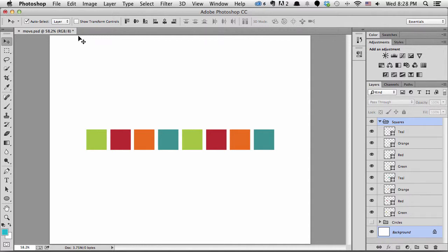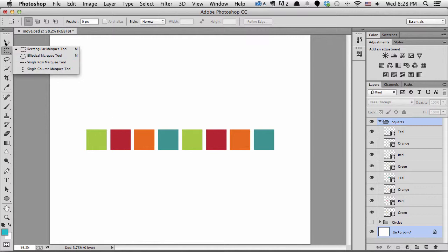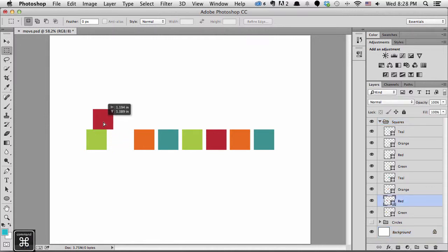The very final thing I want to remind you of is that the Move tool is one of those tools you'll want to grab quickly and use often. Of course, you can use the toolbar or hit the V key to get to it quickly. But you can also hold the Control or Command key down to access the Move tool temporarily. While holding the key down, you can move something, but when you let go of the key, you go back to your previous tool. This is a very handy shortcut to remember and one I use often.